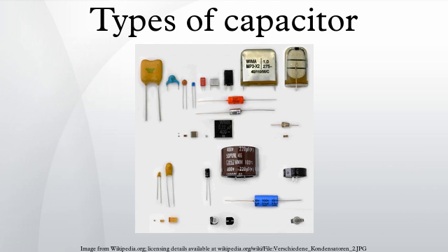Another example is two pieces of insulated wire twisted together. Capacitance values usually range from 3 picofarads to 15 picofarads, used in homemade VHF circuits for oscillation feedback. Specialized devices such as built-in capacitors with metal conductive areas in different layers of a multi-layer printed circuit board and kludges such as twisting together two pieces of insulated wire also exist. Capacitors made by twisting two pieces of insulated wire together are called gimmick capacitors. Gimmick capacitors were used in commercial and amateur radio receivers.